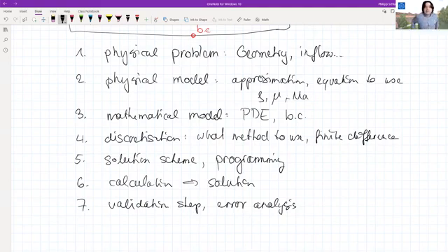Some other errors I do not know. So for instance, typically if I want to reproduce an experiment, I do not know all the details of the experiment, so I don't know what turbulence intensity they had. I don't know exactly what geometry they were using. These types of things are errors which I don't know, but yet I need to come up with an estimate of how good or how bad this was. And of course, I also need to look at the results. So I need to do some sort of post-processing in the sense of analyzing my data, extracting mean values or profiles, whatever is needed, coherent structures perhaps, and so on.